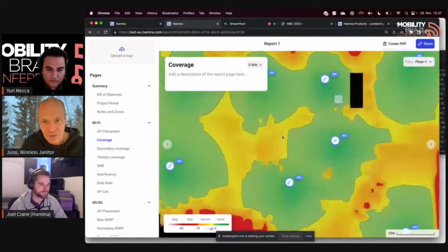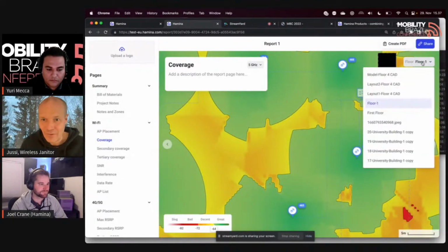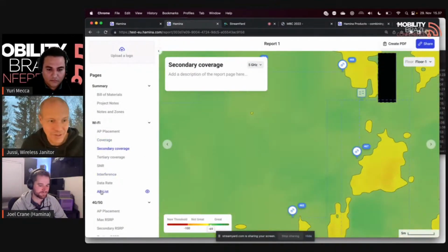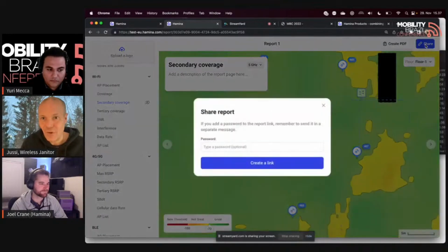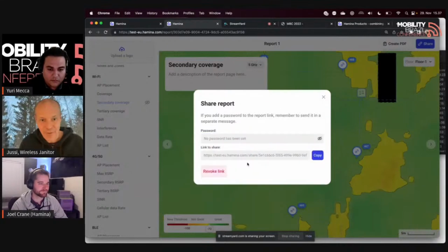I do. So you have the heat maps and everything, floor 1, floor 2, all of that. Primary coverage, secondary coverage. And if you want to hide certain things, no problem. You can easily hide those as well if you don't want the customer to see. And when you're ready for the customer to get the report, you can either create a PDF, or what we recommend is to share the dynamic report. So you just get the link and there you have the report.